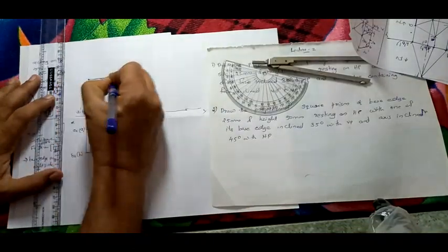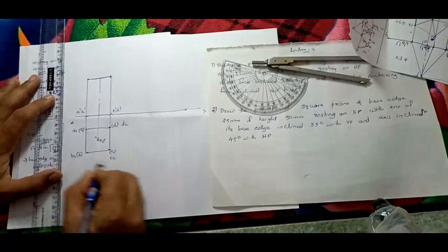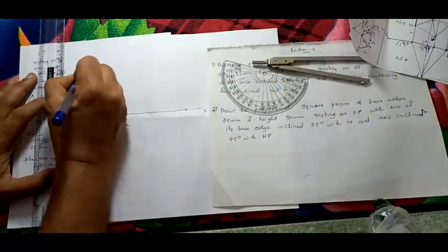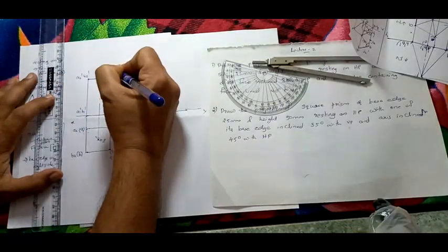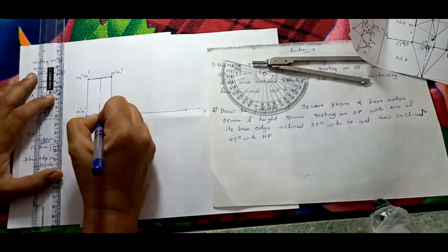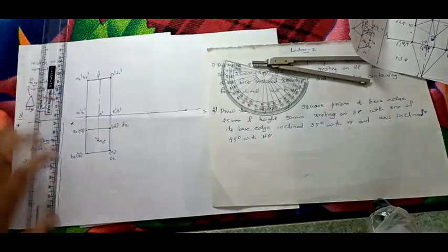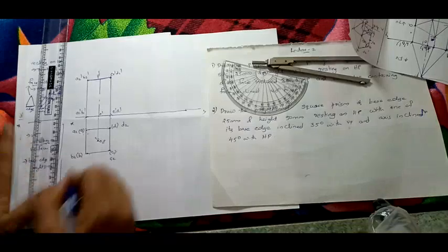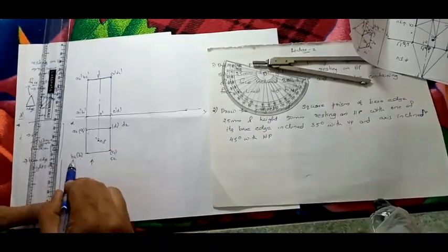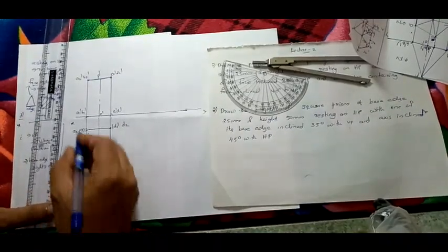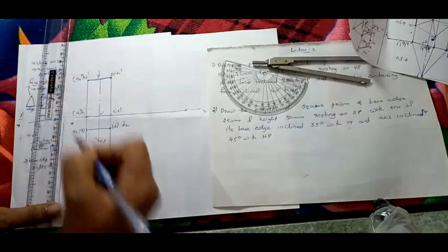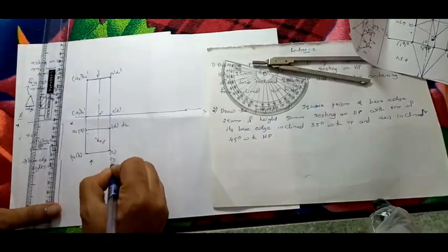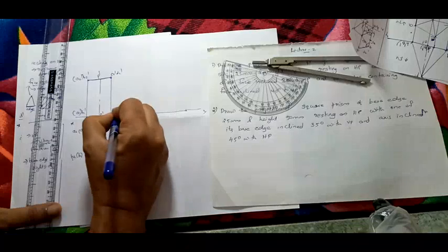And this is your top base, that is A2 B2 C2 D2. So A2 dash B2 dash, sorry, C2 dash D2 dash, and this is the O dash P dash axis. Now which one is visible? If you are looking from here, B1 and B2 are visible and A1 A2 are not visible. So A1 dash A2 dash in brackets. Here C1 C2 are visible, D1 D2 are on the back side. So D1 dash D2 dash.